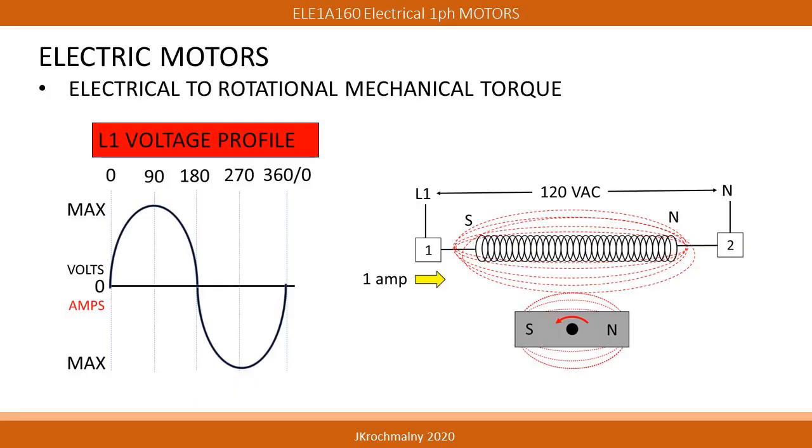Some single-phase motors are built to produce more power for work. If the power of any motor is coming from the force generated by the flux lines, additional force could be accomplished by a technique involving splitting the phase. In this graphic, we see the flux lines of the stator coil impacting with the flux lines of the rotor.